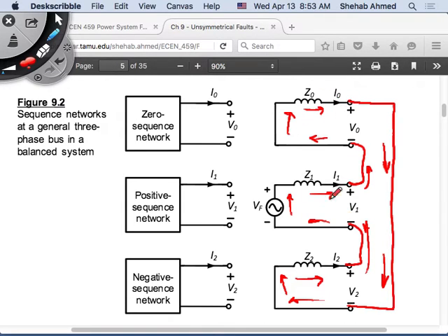And I know my positive sequence current. I know they happen to be equal if I connect them this way, right? So if we take our three-phase circuit, use our assumptions that we have on the initial slide, only the phase with the fault happening through it will have current, the others will have zero. Use those assumptions and see mathematically what the sequence circuits look like in that case. If they end up being something like this for one of the cases, then in this case I know that the positive, negative, and zero sequence currents are the same.